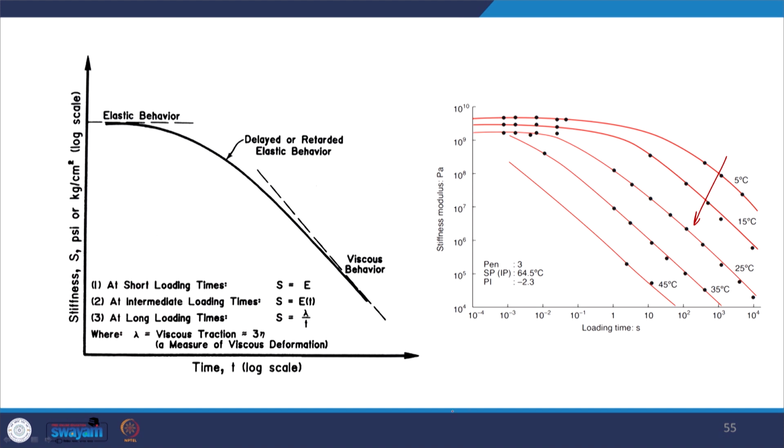If we consider the 3D stress strain system, the response or this particular variation will be more complex in nature. However, for most of the purposes, it is found that a uniaxial stress system is adequate to study the response of the bitumen and therefore the bituminous mixture.